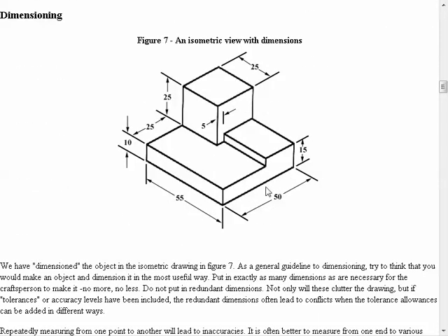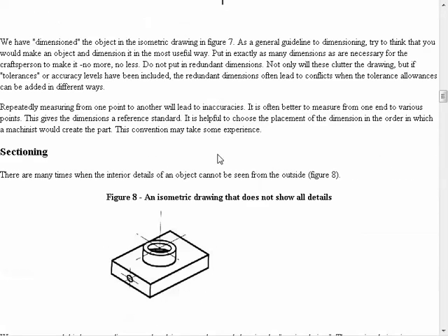In some cases, an isometric drawing with size information called dimensions placed in the various directions could fully describe the nominal geometry of a part. But this is not the traditional engineering way to create a drawing of a part that is sent to people who will end up making this part. The more traditional way is to make the 3-view of the part, the 3 orthographic views, and place dimensions in the appropriate orthographic views.